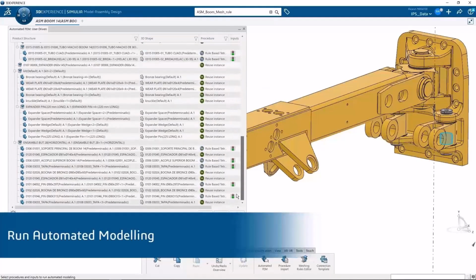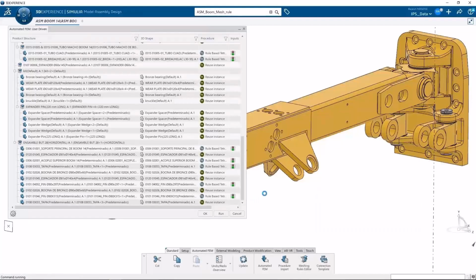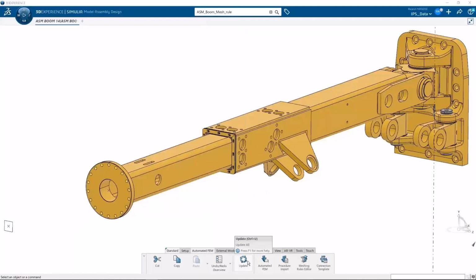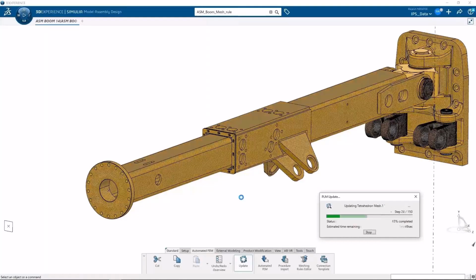And you'll see the same thing for when you mesh. There's one click on an update button, and you can watch this mesh generate from part to part. Generally, I use my local resources for meshing. It happens very fast, and usually it's faster than even on the SOLIDWORKS side. And because this goes part by part, and you've got the local control too, if something fails to mesh, you'll notice on this one part, it's not going to fail over the entire assembly.